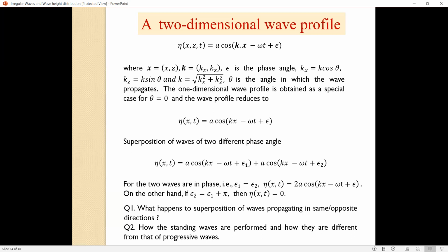Sometimes you take a box type structure, you reverse the box and put it in the water body with a particular length and width, and you can again create a phase lag. How to develop a phase lag when one wave is propagating, how to create a phase lag so that you can add the effect. And this concept has been generalized. This is simple physics, but you look at its repercussion when you make a problem work, that is where engineering innovation comes in.